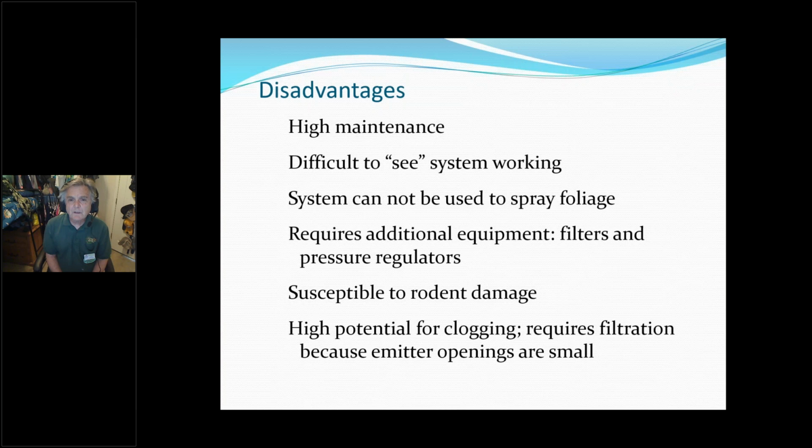There are some additional parts that you would add to the system. Certainly a filter. A filter would remove any debris or sediment. And pressure regulators, if you are running your system directly from the street without going through a regulator, because drip irrigation can run on much less pressure.